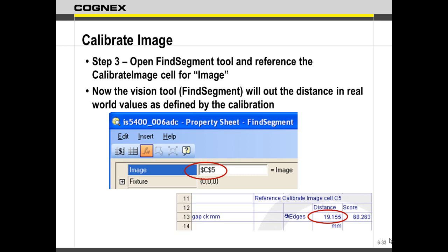But if you needed it to also spit out what the real world coordinates are, then what I would do is copy and paste it, take the second one, calibrate that, and leave the first one set in pixels so it can still control the others. The only gotcha on that one is if you change one of the functions, you need to make sure you change the other. Otherwise, you've just disconnected them from each other and they won't be doing the same thing.